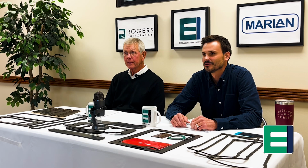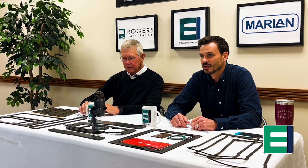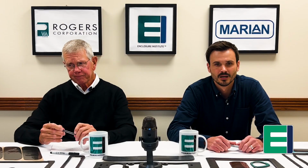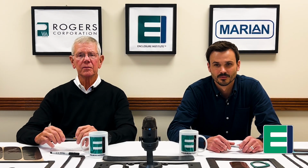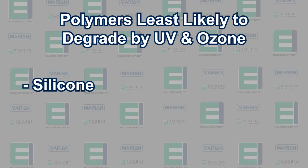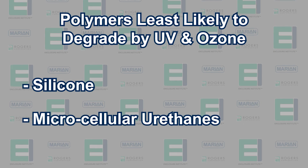If your device and gasket will be used outdoors, installed on rooftops as a part of exterior signage or any other application where prolonged exposure to the sun is involved, you should design with a material rated highly for UV resistance. Imagine a gasket in an aluminum frame exposed to midday sun and midnight frost. The seal must flex and rebound through thermal expansion cycles while resisting UV damage year-round. Silicone polymers will provide the longest lasting performance, and some microcellular urethanes do quite well.